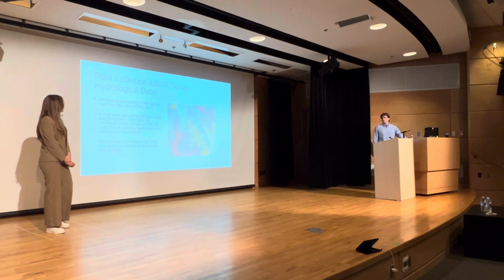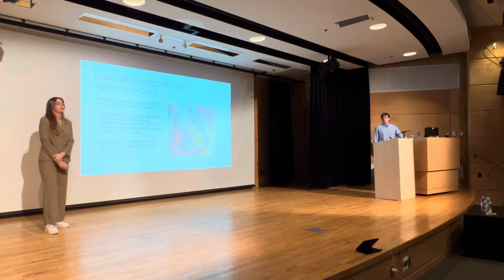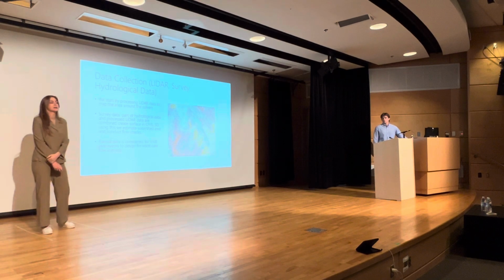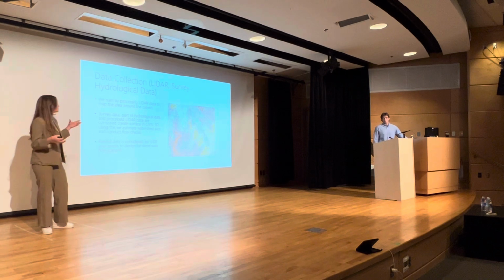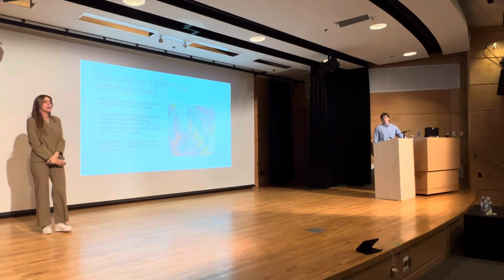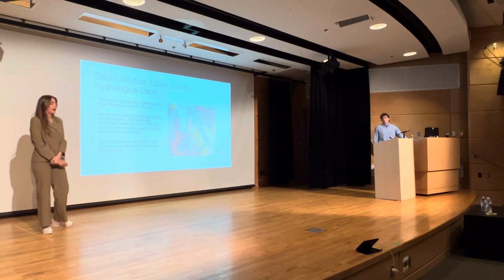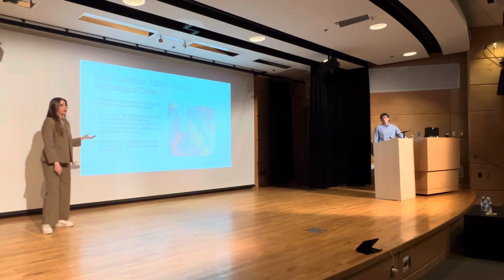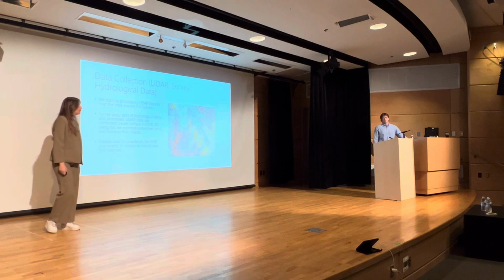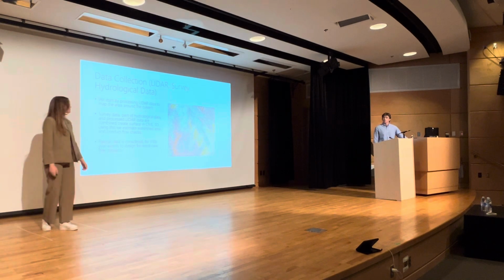Taking those into account, we will do calculations, and we will also take rainfall data into account for 1 to 100 year events. What a 1 to 100 year event is, it's not that this intensity of the rainfall will happen every 100 years. It's just that there's a 1% chance of it happening in any given year. And we design for this because of Halifax Water guidelines, and also because it's the worst case flow scenario. So we have to make sure that the culvert can handle all flow scenarios.